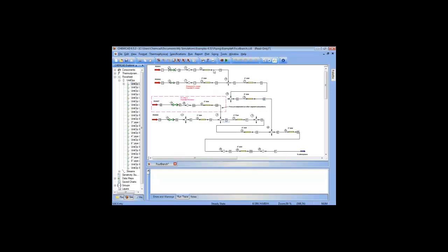And you can see how if flow is coming through multiple lines, how it starts to affect the back pressure on other lines and things like that. Those can all be done in an analysis with nodes and with the pipe network. Again, just a couple of different examples beyond what we've shown to see additional uses of the tools.